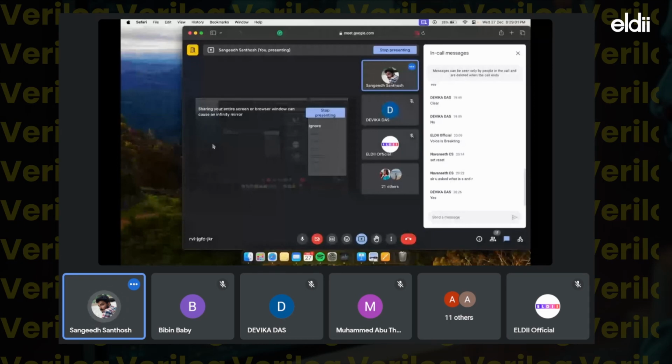For example, I already explained, in the case of an if else block, if I am representing if control is 1, we need to execute this. We are not representing what happens if control is 0. In that case, if control takes the value 0, it will be going to a buffer. So for every signal, if we are taking it as a control or expression signal, we need to provide every possible combination.